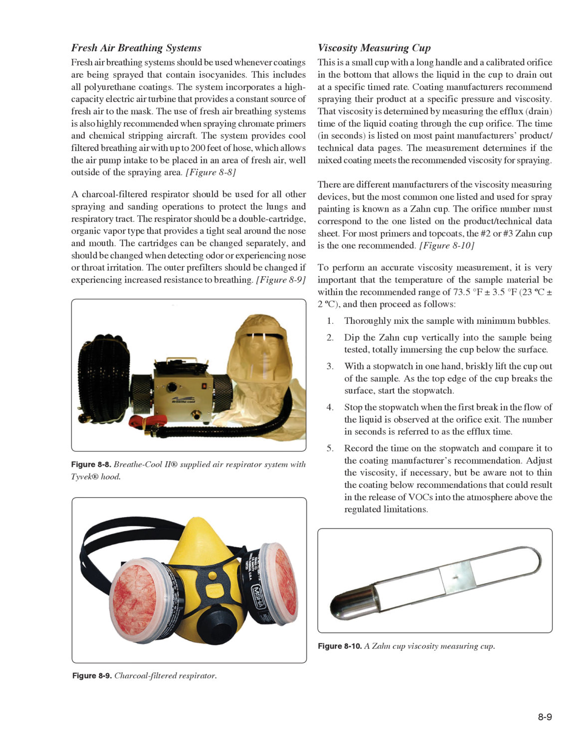3. With a stopwatch in one hand, briskly lift the cup out of the sample. As the top edge of the cup breaks the surface, start the stopwatch. 4. Stop the stopwatch when the first break in the flow of the liquid is observed at the orifice exit. The number in seconds is referred to as the efflux time. 5. Record the time on the stopwatch and compare it to the coating manufacturer's recommendation. Adjust the viscosity, if necessary, but be aware not to thin the coating below recommendations, which could result in the release of VOCs into the atmosphere above the regulated limitations.